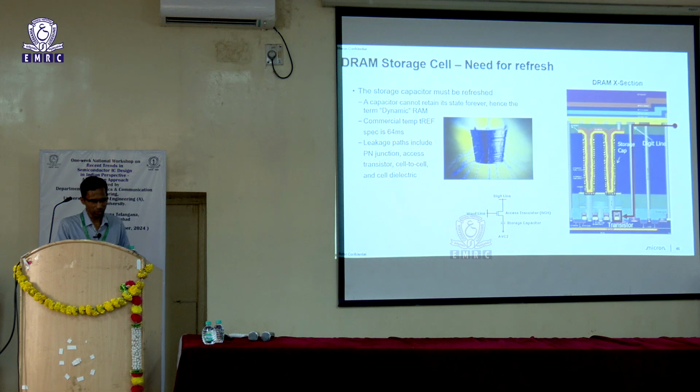And we talked about this before. DRAM is dynamic in nature, and there is charge leakage involved. There are multiple leakage mechanisms. The figure on the right shows a typical cross section of a DRAM cell. This is your storage cap built in the middle of the line. This is where your transistor resides. Then you start your middle of the line, and then this is the back end of the line. This is how a capacitor is constructed here, and then it gets interfaced with your transistor. This is your 1T 1C cell, and there are multiple leakage mechanisms.